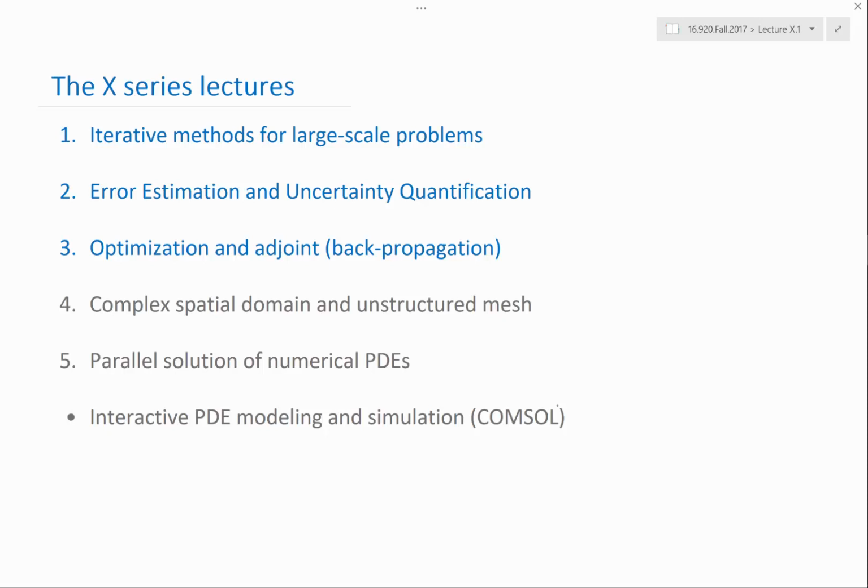We want to solve the PDE for the purpose of changing the geometry to make it better. And even in scientific problems, there can be parameters you want to estimate that you don't know. You can only estimate the parameters by assuming the parameter is that value, solving the PDE, and comparing the results with experimental results. If it doesn't match, that means your parameters are probably not right.